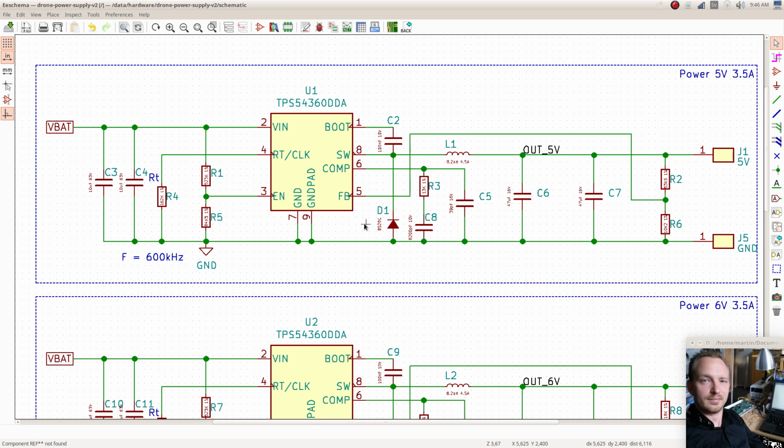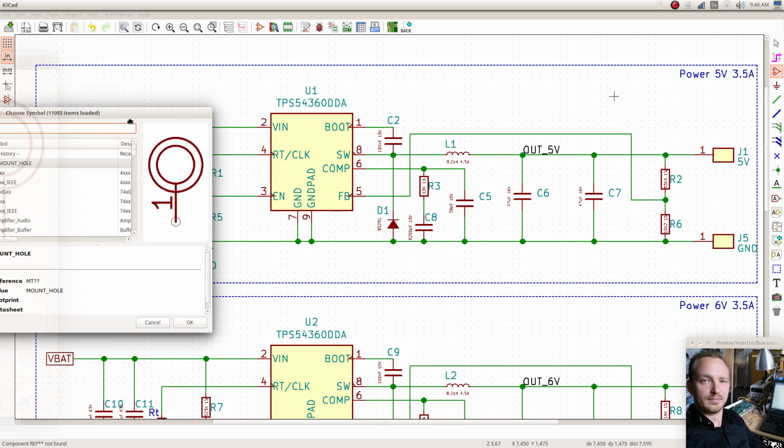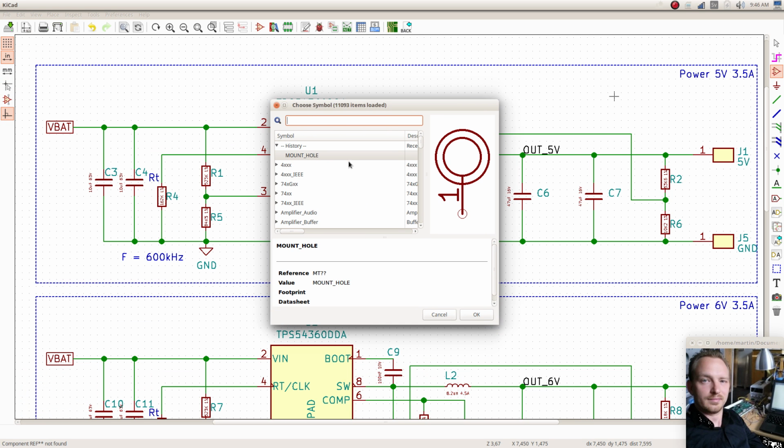I think that the official KiCad library should be seen as a template library. All of the components in the official KiCad libraries should be just templates for standard components. In a lot of ways that's already the way it is, but I don't think that people view it that way by default. They see it as a library of components they should use directly in their schematic, which is a very bad workflow.